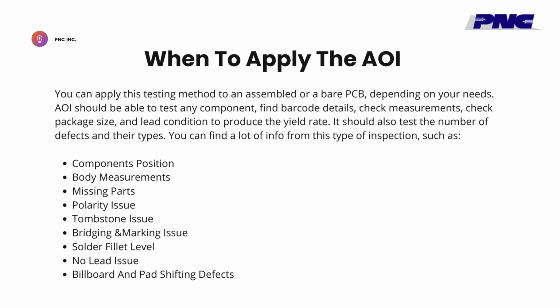You can find a lot of info from this type of inspection, such as components position, body measurements, missing parts, polarity issue, tombstone issue, bridging and marking issue, solder fillet level, no lead issue, billboard and pad shifting defects.